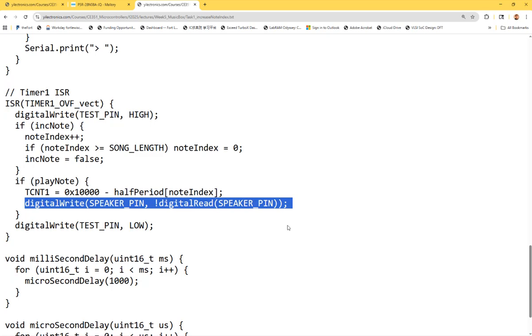So my question is, is the timer actually waiting here until the timer is done, or is it going to run this line immediately? Immediately, okay. So there's no while loop. Why would it wait, right? There's no mechanism to wait. It's still within that interrupt function. This is just a number being set up to the timer counts. So it's running behind the scenes, right?